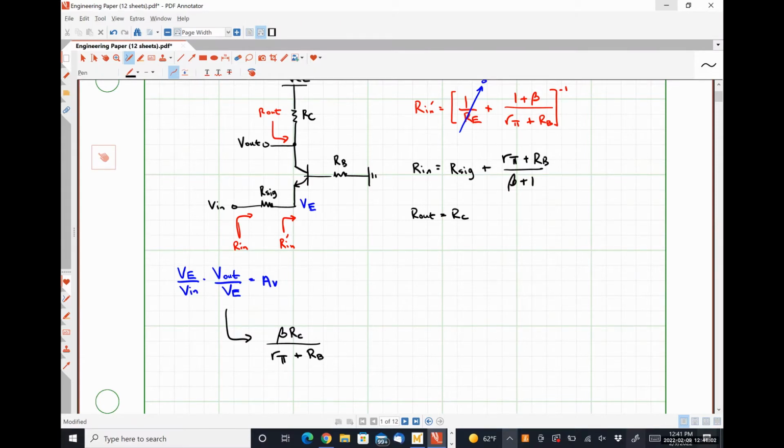This is going to be our new denominator for our voltage division relationship, our transfer function relationship. And the numerator is just going to be this part, because we're looking for the voltage drop from this node with respect to ground, over R sig in series with this guy over here.